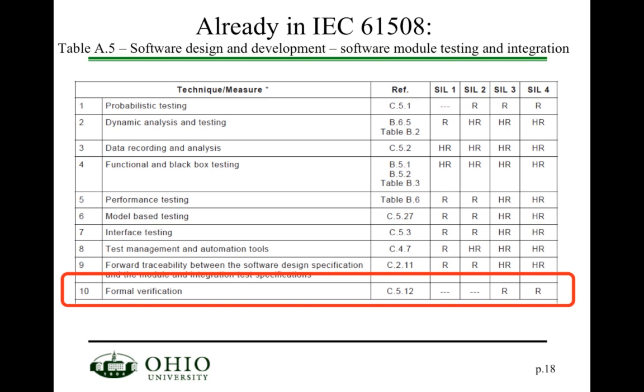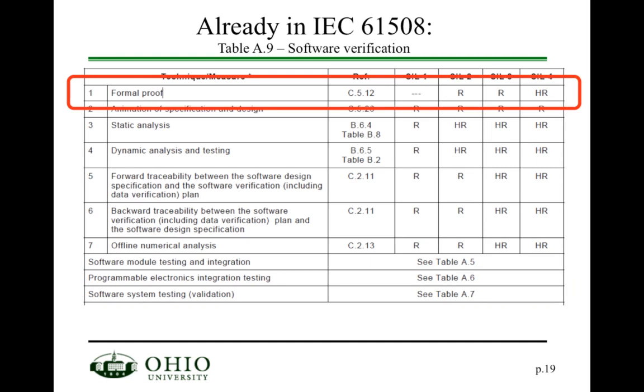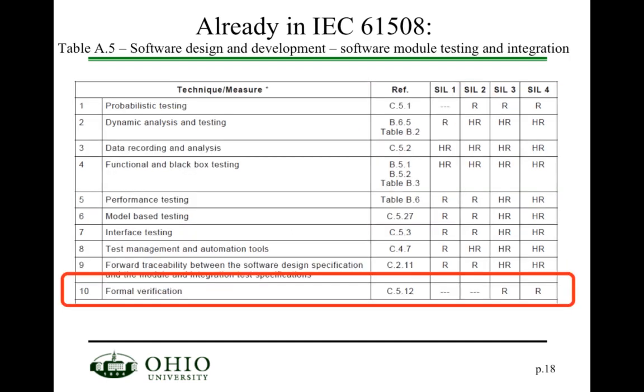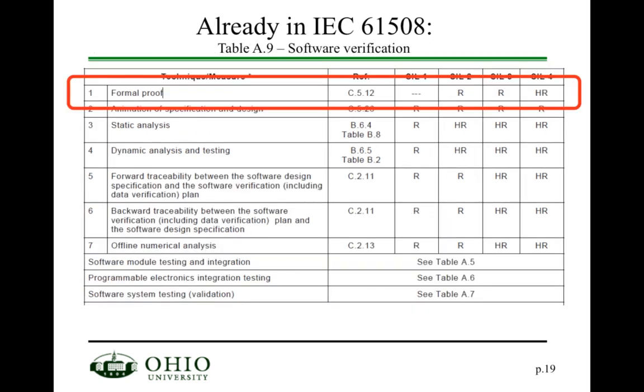Now, in 61508 we already saw formal methods. Formal verification is recommended for SIL 3 and SIL 4, and formal proofs are highly recommended for SIL 4.